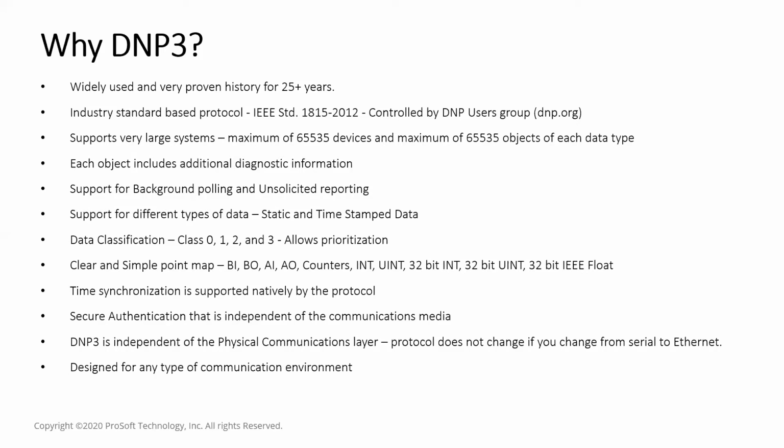This would help with things like scheduled maintenance, planning downtimes, reducing the mean time to repair, and with predictive maintenance as well. The protocol allows users to classify data, and the reason you can do that is because this is a push and a pull protocol. What I mean by that is you can have outstations that have the ability to send data when there is an alarm.